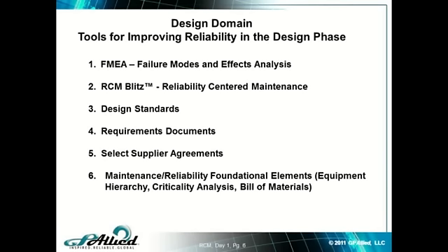I've always said, as a person in operations and maintenance, I would have loved to have just one time a piece of equipment delivered that had a complete maintenance strategy with it. So once it hit the floor and was running, we knew what PMs we should do. We knew what predictive maintenance tasks we were going to do, right? We knew what the operator checklist should look like. Most places wait for the equipment to be installed before they ever start talking about that. Design standards, right? Design standards get into, again, foundational issues. How much support do we need there? What type of base are we going to use?